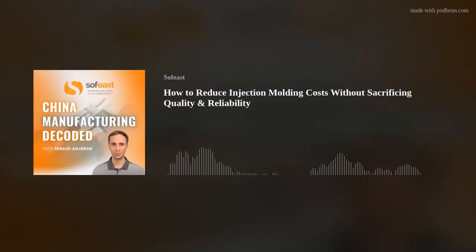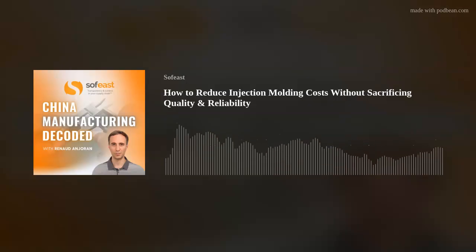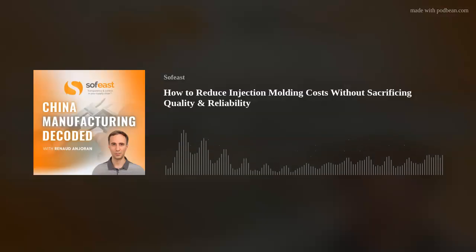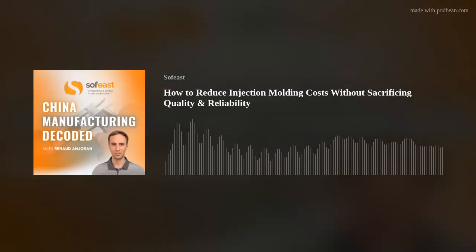I talked about sitting at my dining room table, and half of the dining room table is a big tool. It's a big tool, but obviously there are a lot of smaller tools. Now, if you've got a tool that is capable of being run on a 90-ton machine, and that's the optimum size machine, you wouldn't necessarily want to run that on your 210-ton machine. You could quite easily. That's not a problem. But with the efficiency, the amount of energy that machine is using, you're paying for additional energy to run the bigger machine where you don't need to.